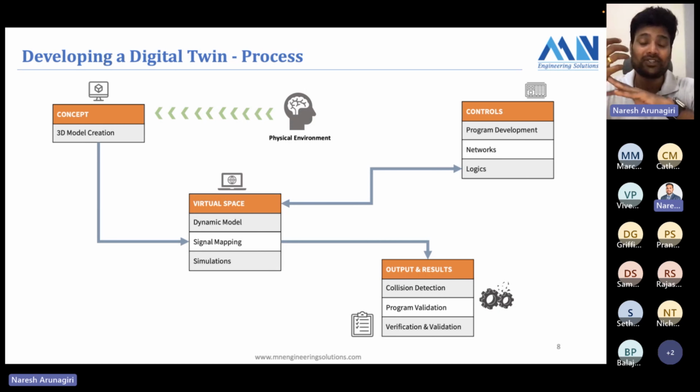The second is program validation. That's our main concept. We got to commission the program so that when they have the actual machine in place, we can just plug the program in, and it's already 95% commissioned. When I say 95% commissioned, you got to do minor tweaks for the manufacturing process. Obviously there are going to be stack-ups and tolerances to it. So you just do some small tweaks, and then the machine is ready for the final FAT. So these are the benefits.